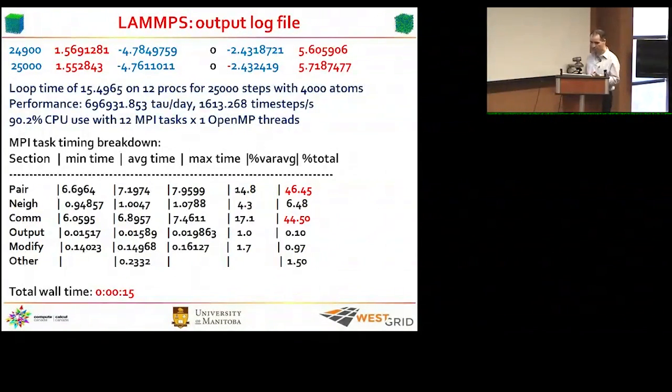So from this you know that this program takes this time to run this number of steps. This information can be used to set the wall time when you run your program. So if I run the simulation for, for example, 1 week, I can set the maximum number of steps according to this information.